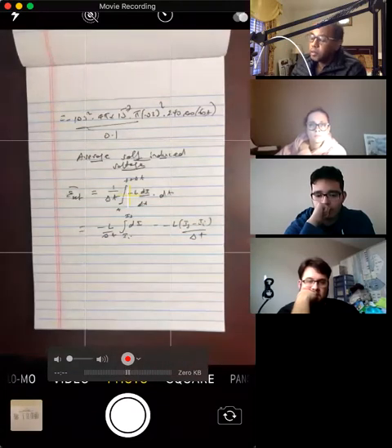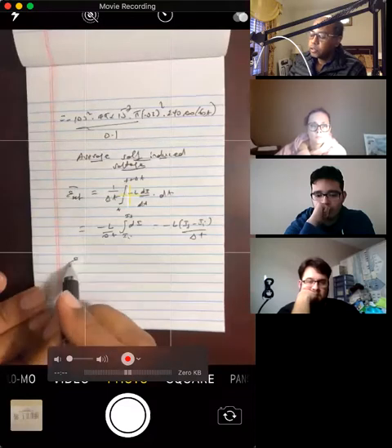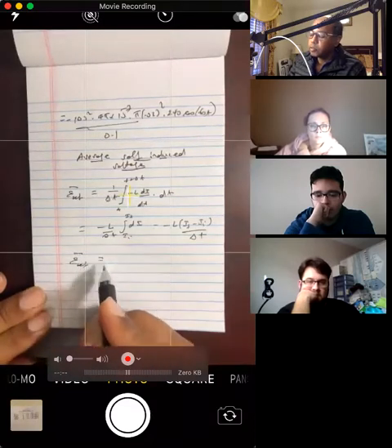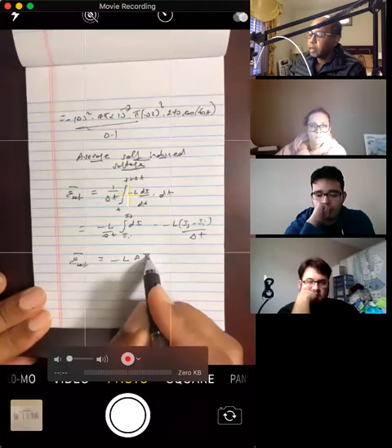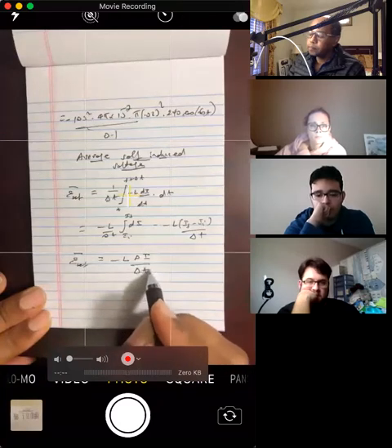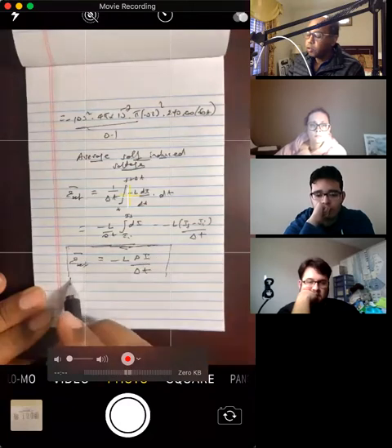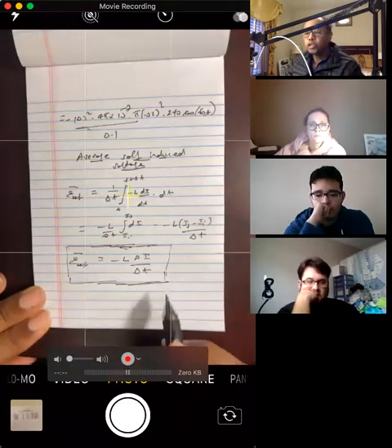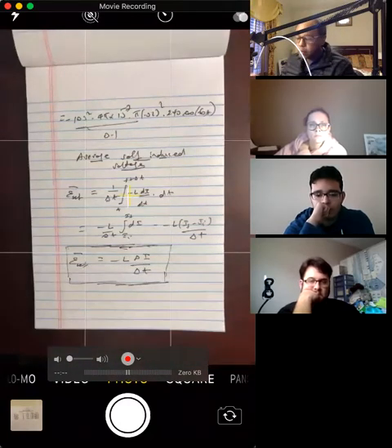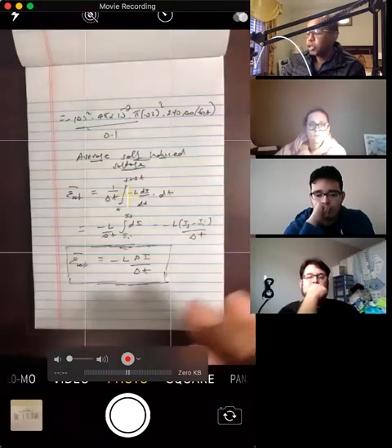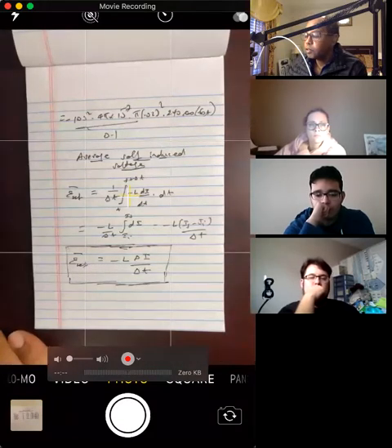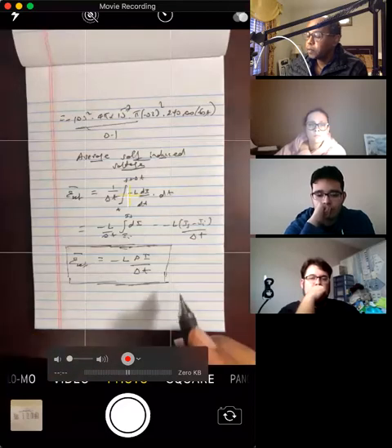So the average self-induced voltage is simply negative L delta I by delta t. If you're interested in the average, all you need is the initial current, the final current, and the time taken for that change, and that'll give you the self-induced voltage.